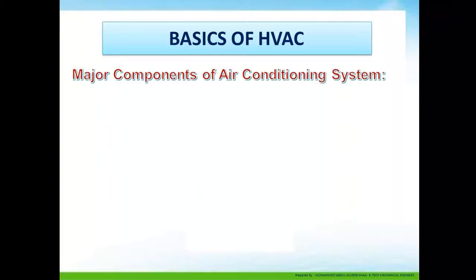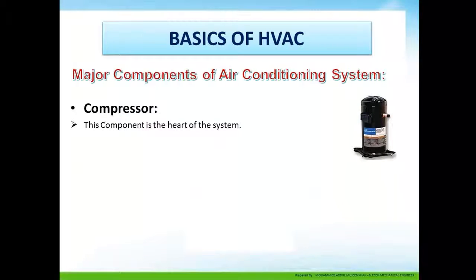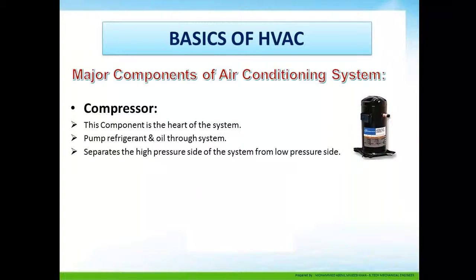Major components of air conditioning. Compressor. This component is the heart of the system. It pumps refrigerant and oil through the system and separates the high pressure side of the system from the low pressure side. If it fails, no cooling takes place.